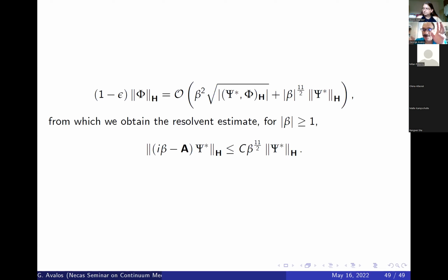For uncoupled fluid flow, you have an associated pressure, which is unique modulo a constant. For these coupled structure problems with Stokes flow, you're not speaking about a pressure, you're talking about the pressure. There's no uniqueness modulo a constant, there's only uniqueness.